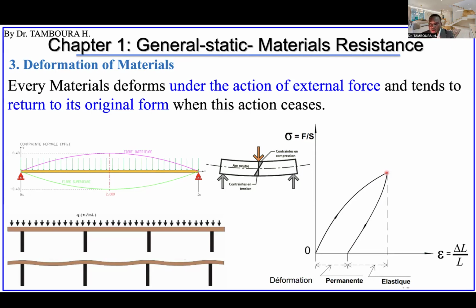Once you stop, the material will try to recover its original shape, so it will come back this way. However, the material will not recover all the deformation that the applied force caused. So the recovery will not follow the same path, and it will not be at the same speed of recovering.